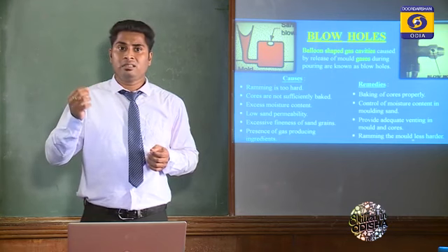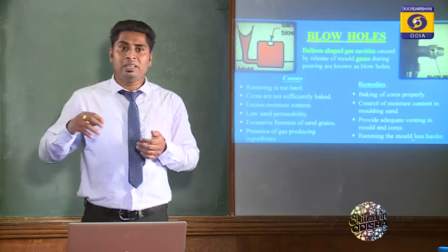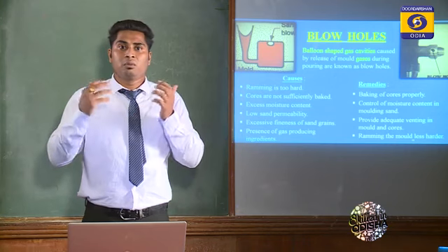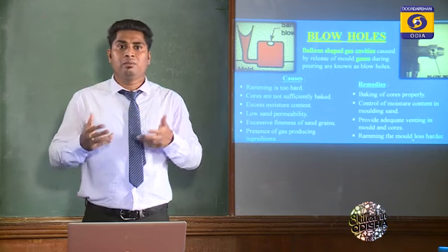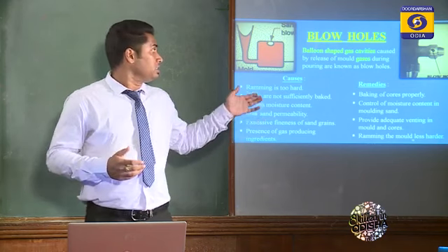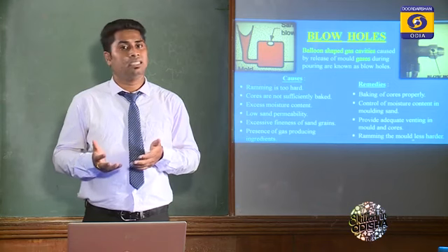By creating small holes, the mold gas can be easily removed so that blowholes can be prevented. By using these remedies, we can avoid blowhole casting defects.